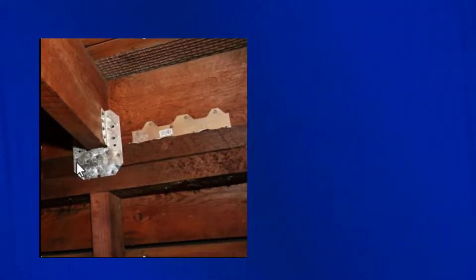Here you see 2 floor connectors. This right here is the top of the cripple wall. Now this floor connector here is called a type E connector in the FEMA P1100. And the way this works is this nail and then this nail and then this nail, they nail into this board right here. And there's some other nails that come down this way. And when they come down this way, they attach to the top of the cripple wall. And that way, when the floor tries to move, it goes into this type E connector, and then that goes into the top of the cripple wall, which is what we want to have happen.